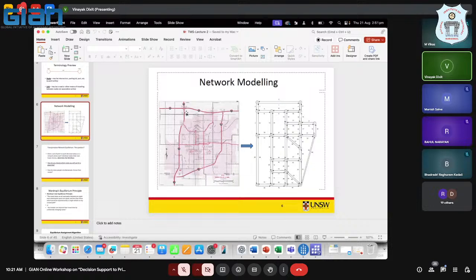The reason why equal travel time is important is that it applies only to the used paths. You also have this path here. This is an unused path, so there will be no vehicle on it, and the travel time is much larger.